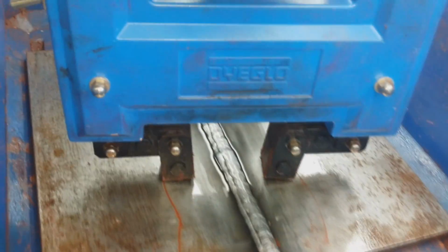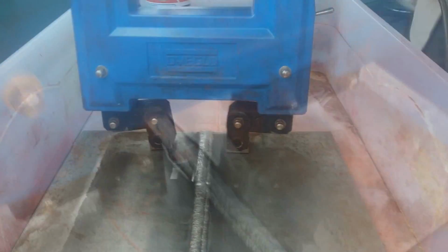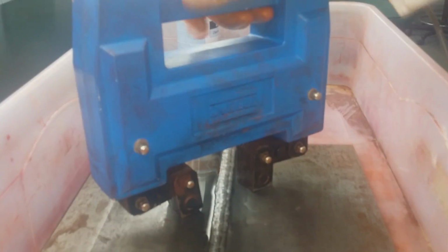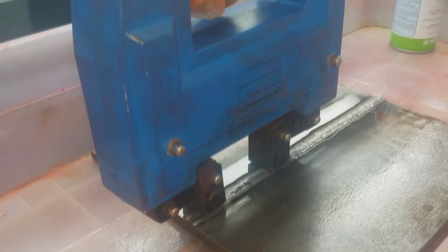While the yoke is still energized, gently wash away excess. Observe the inspection area during this process to witness indication formation. Evaluate indications to specification criteria prior to yoke reorientation. Turn the yoke 90 degrees and repeat steps 1 through 6.